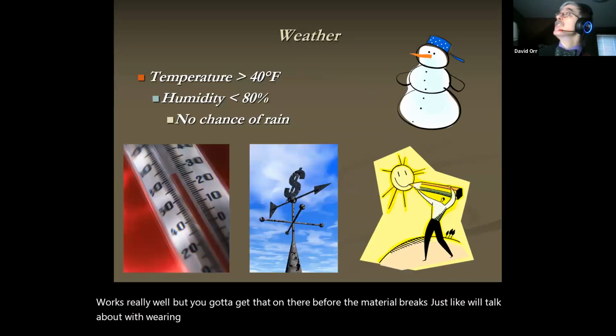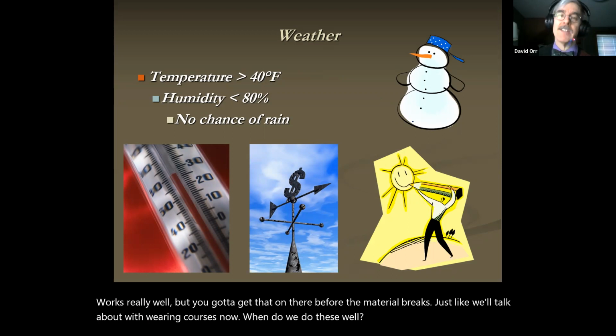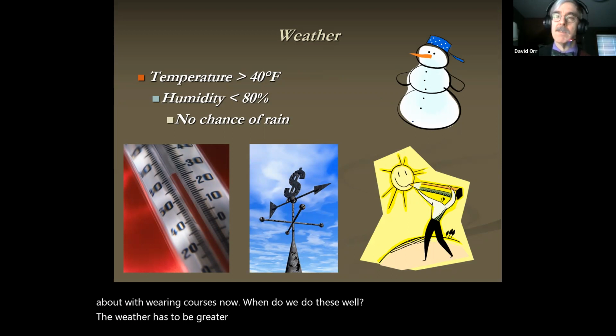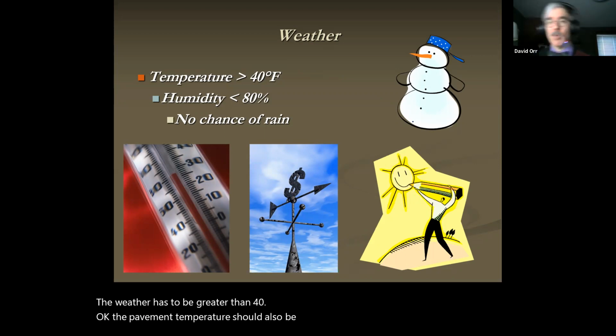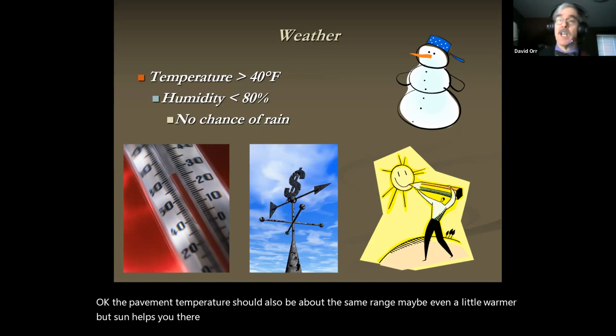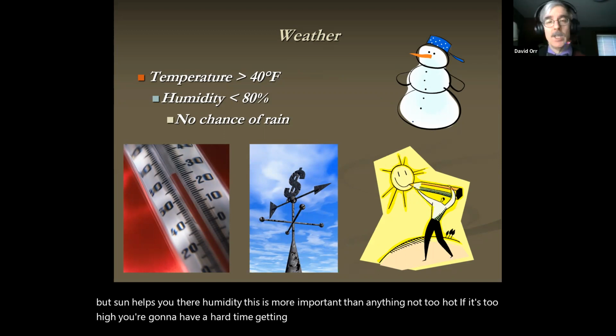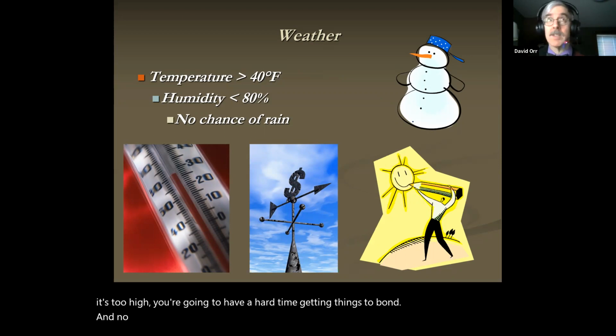Now, when do we do these? Well, the weather has to be greater than 40, okay? The pavement temperature should also be about the same range, maybe even a little warmer, but sun helps you there. Humidity, this is more important than anything, not too high. If it's too high, you're going to have a hard time getting things to bond. And no chance of rain whatsoever, okay?